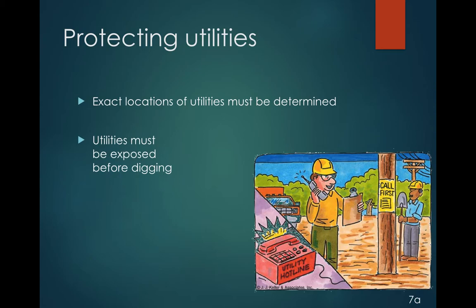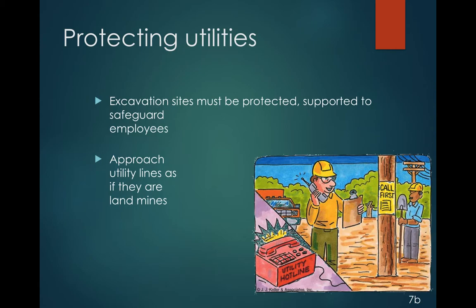I want to mention this: the exact locations of utilities must be determined, and utilities must be exposed before any digging can commence. Excavation sites must be protected and supported to safeguard the employees, and approach utility lines as if they are landmines.